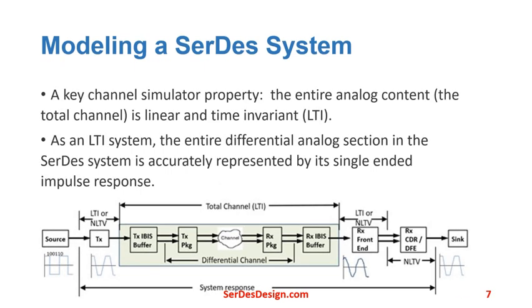Modeling a SerDes system. A key channel simulator property to keep in mind is that it considers the entire analog content, the green area in this figure, the total channel between the TX-AMI portion and the Rx-AMI portion, to be linear and time invariant. As an LTI system, the entire differential analog section of the SerDes system is accurately represented by its single-ended impulse response. This key concept enables the channel simulator to achieve its fast simulation speeds.